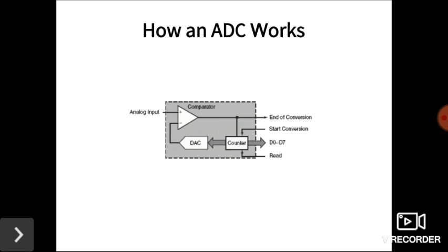Generally a start conversion signal is necessary to initiate the whole process, and a read signal is necessary to read the data. Such a procedure depends on sequential logic demanding a clock signal, which is generally supplied from an external source. The whole procedure in the ramp method takes a finite amount of time, not instantaneous like a DAC. However, a flash converter type ADC is capable of converting analog inputs to digital form almost instantly, using different techniques.